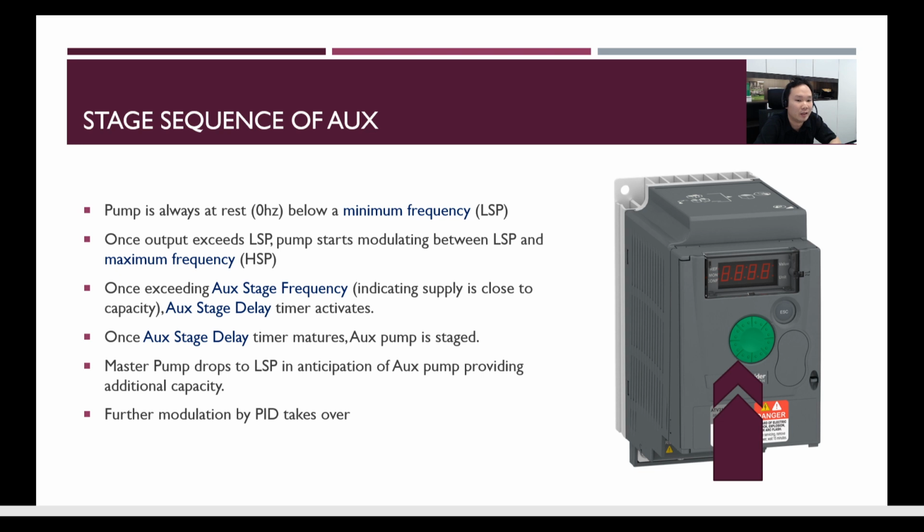We will delay the destaging part, because when you're having a shower, your neighbor flushes the toilet, the upstairs neighbor starts washing his dishes. So we don't want to wait for the auxiliary pump to come in. We want it to come in immediately. All right. If not, you're going to have a not so pleasant shower session.